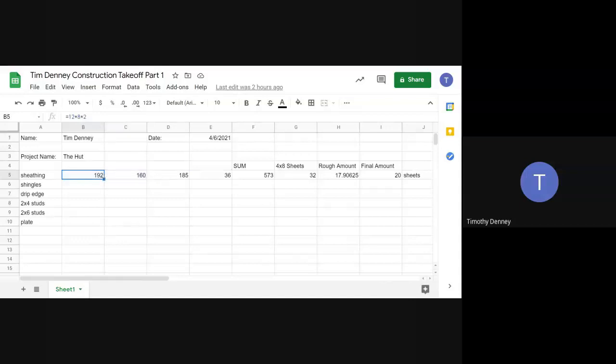We had one wall that was a 12x8 wall, and because it was a box building, there's two of those walls, one on either side. That's why we multiplied by 2. And then there's also the other two walls of our building that were 10x8 feet, and we had 2 of those, so multiply that by 2. Because they're rectangles, all we had to do was length times width, 10 times 8. And so that was our outside walls.